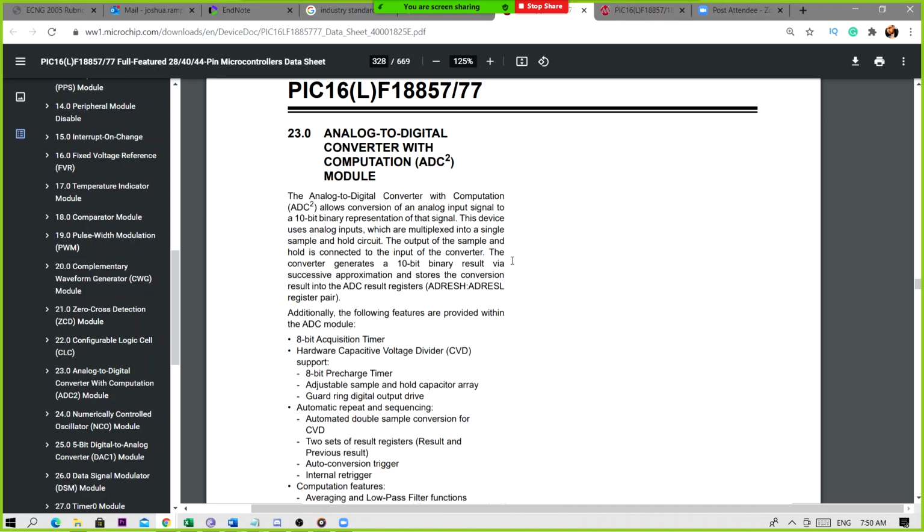Yes? Yeah. All right. So what they're saying is, if it's a digital input signal, then we would talk high and low, and we would use VOH and VIH and VOL and VIL to talk about digital signals, right? Yeah. This peripheral is going to deal with analog input signals. So in other words, we're not getting high and low. We're going to get some number, a 10-bit number, that will vary based on the voltage. Okay. Read the next sentence.